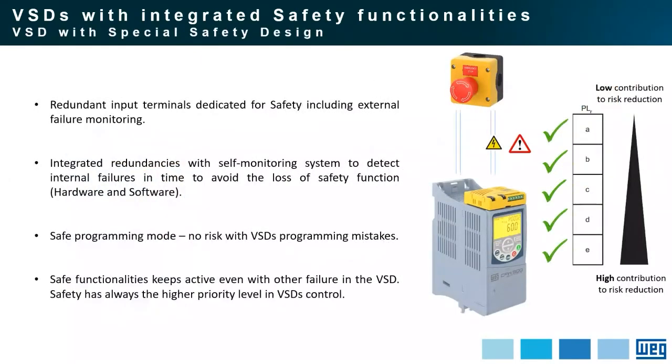But in the end, how can the variable speed drive control it in a safe way, and comply with all the safety standards? So internally, or let me start with externally, the variable speed drive has redundant input terminals dedicated for safety, including the external failure monitoring.